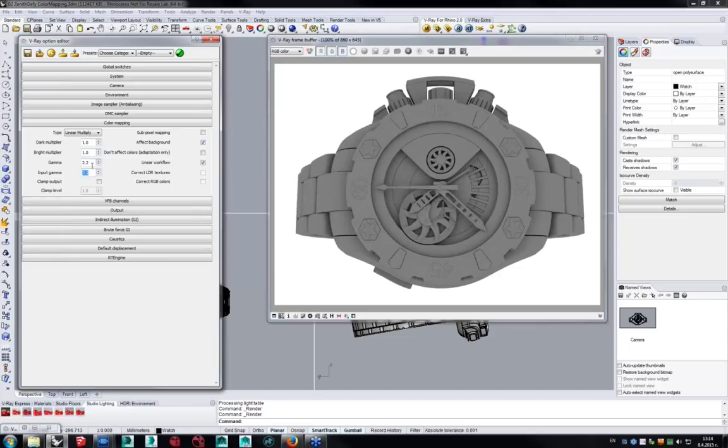So everything that is being plugged in, like HDRIs, actually HDRIs most of the time are linear, but let's say I'm working with JPEG, PNG, TIFF images, these all need to be gamma corrected so they can be rendered linearly and then have gamma 2.2 applied at the end. So this is the linear workflow that I can disable.